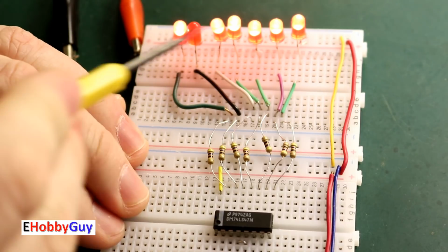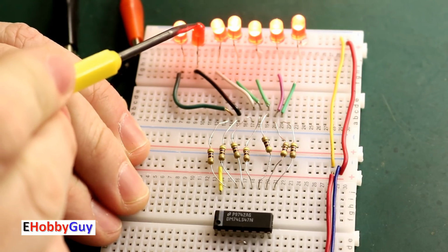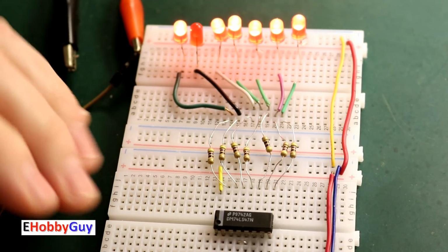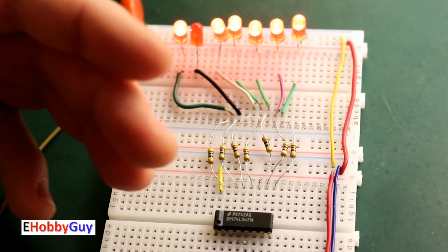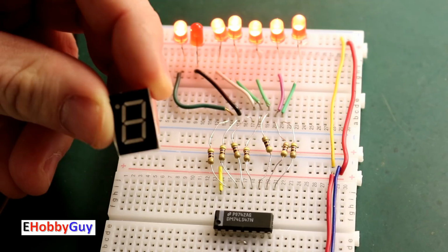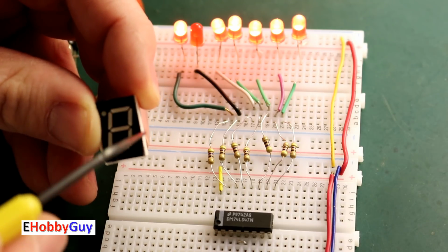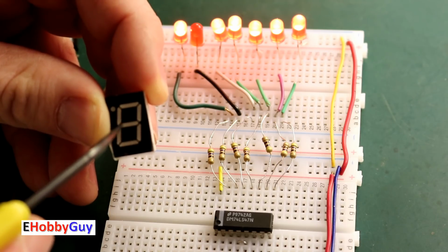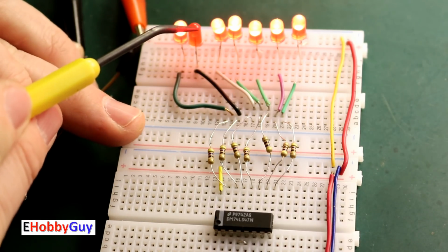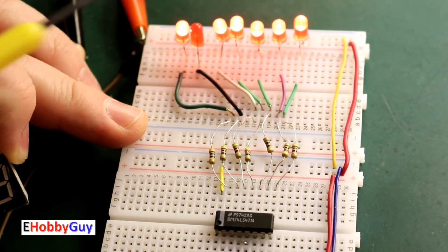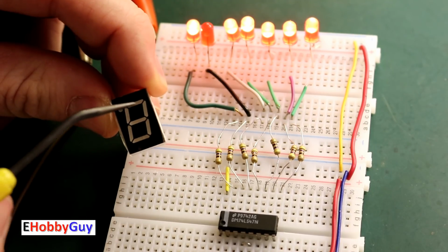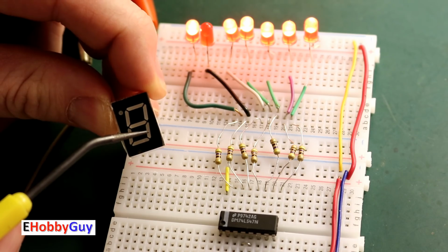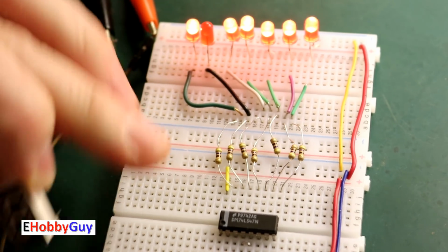And so looking at the output here, we have one LED that's out. Now I'm not pressing any buttons at all. And what that means is that a 0 should be displayed on a 7-segment display like this. And if you look at it on a 7-segment display, all should be lit except the center LED, which is a G. This is the G, and so it is looking promising right now. All are lit. If I press the 1, starting here, A, B, C, B and C should be the only ones that are lit. So let me press a 1 right now.